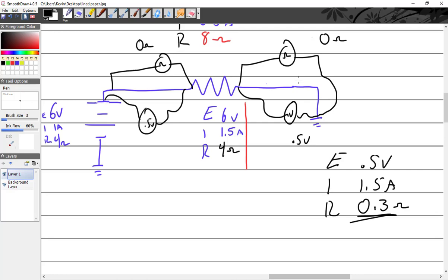The more power you put through this wire, the more resistance you're going to start to notice. When you're only putting a tiny bit of voltage through at the ohm meter, you really see very negligible resistance. But when you put 10, 15, 20 amps through something, the resistance suddenly shows up in these wires. Well, how can you measure that? I know, hook it up to the battery and just hook the ohm meter up while turning, right? Give it a shot. If you're going to do that, call me, let me know.